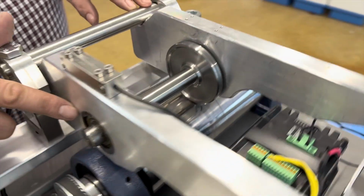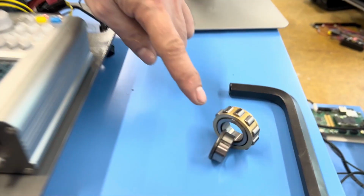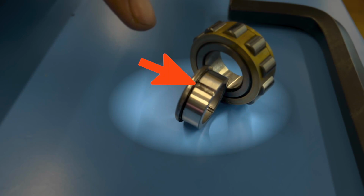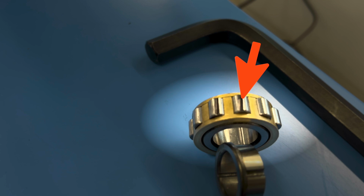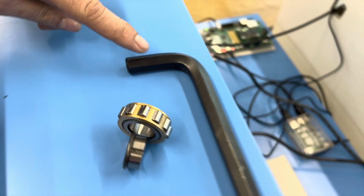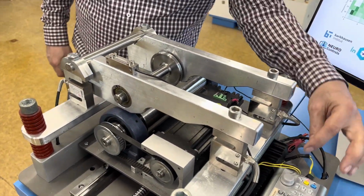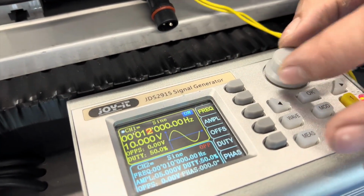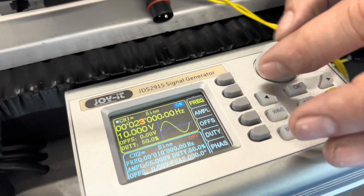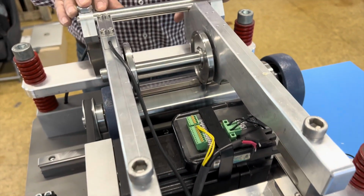We can also change the bearings, and the bearings can be changed here with different faults, like an inner fault and a bearing fault. We can adjust the weight, the load, via these screws, and of course we can adjust the speed. So let's go to 30 kph. Now we are in the fault-free situation.